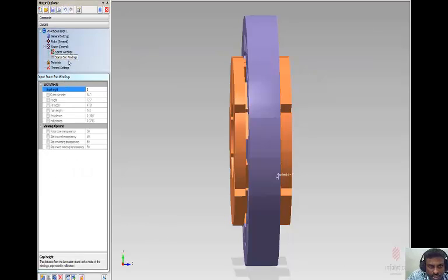After that, the final stage is to incorporate the stator end windings. In the stator end windings, you can see the rotor core and the stator coil, and the distance between these two, the gap height, is going to be 2 mm, along with the height of the end coil.